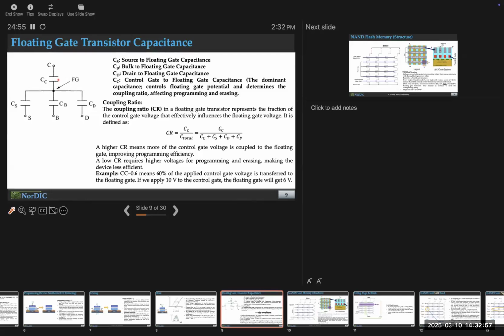So basically, can I handle the expense? Hafnium oxide will have to be made by a different process than silicon oxide. You cannot make them in the same place. I can make a design choice, just a thicker silicon oxide, thinner silicon oxide, or hafnium oxide, silicon oxide, if you can afford it. Okay. I cannot definitively say that nobody is attempting multiple oxides, but I cannot even tell you that they are, because it could be a trade secret. Are you guys all with me so far?